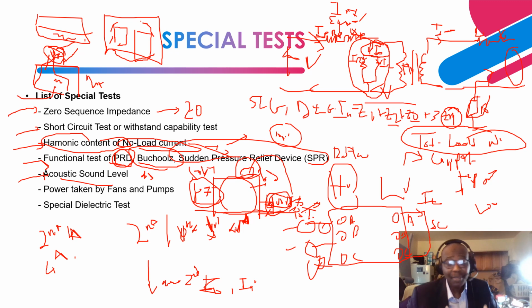So determining the sound level of the transformer is all based on the core of the transformer: the core material, and the arrangement of the core material, the laminations. Because if you have the flux traversing the path of the core laminations, that is where it creates that noise. It's called chattering noise. So it's all based on the type of core material, the laminations, the arrangement of the laminations, and also basically clamping of the laminations tightly to prevent that chattering noise.